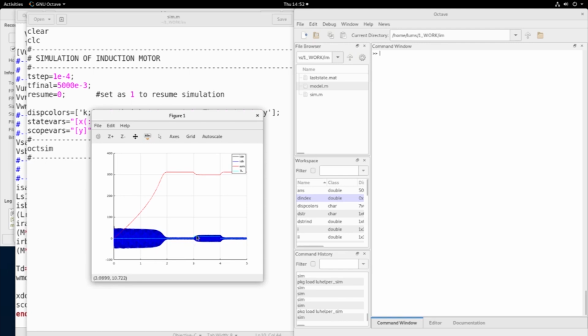So during the torque, the stator current increases, which is again expected, and there is also a drop in omega, because you have B omega. There is a friction loss, and friction is into omega, and as the load changes, omega changes, you will see a change in that drop also, and as a consequence there will be variation in the omega in the open loop.